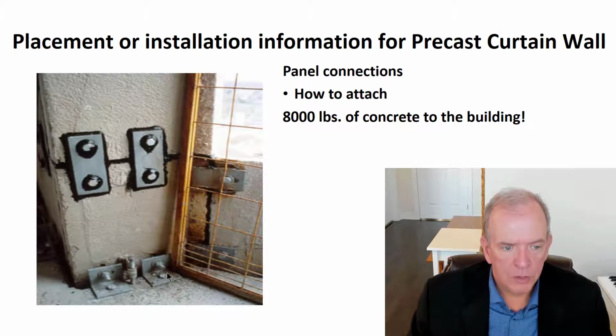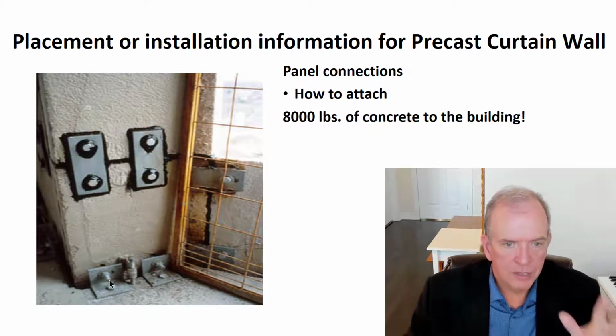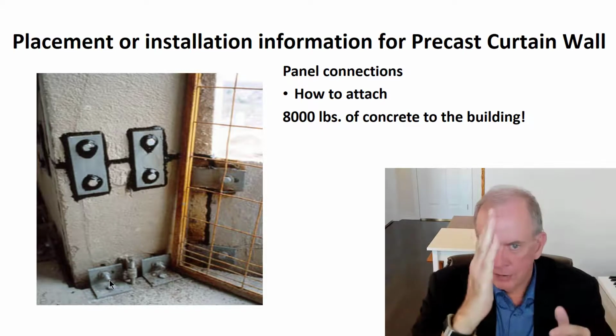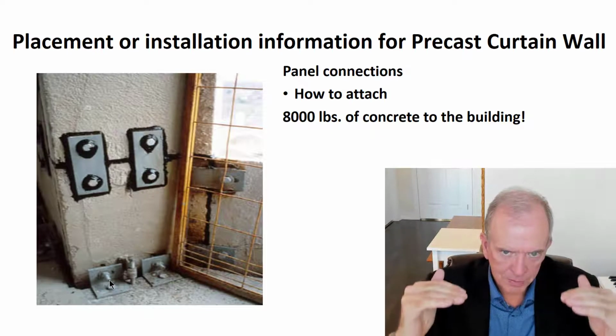And then those are basically your load-bearing connector points and your lateral connector points. These are your joining connections between the pre-slab panels, right? So this is carrying the weight, but it can also be adjusted slightly, and this can be adjusted in and out. So again, if your slabs are a little out, you've got a little bit of adjustment this way, and you can adjust a little bit this way.